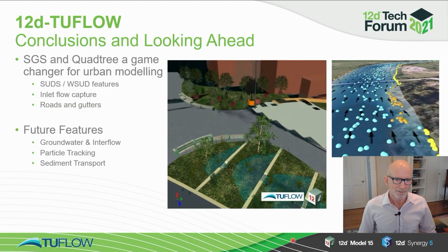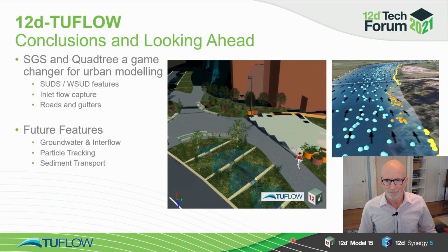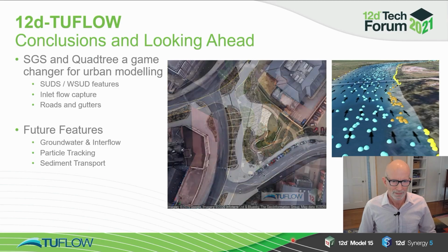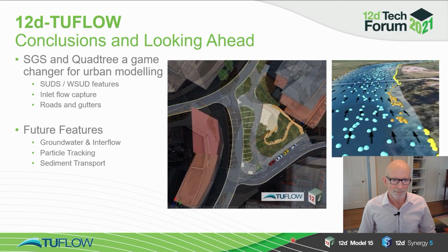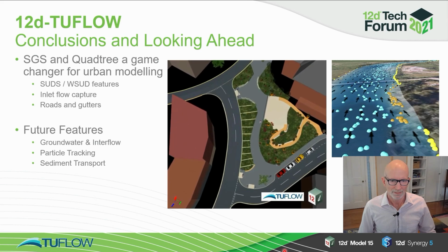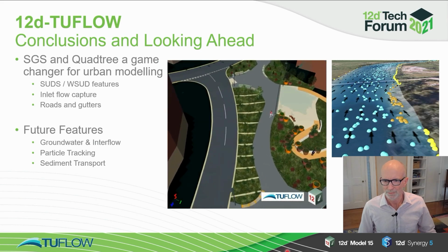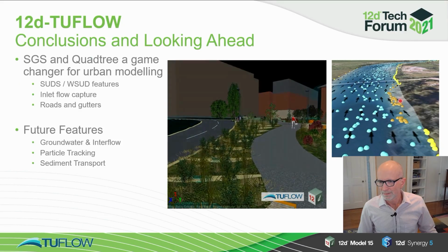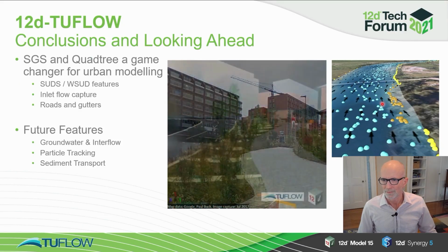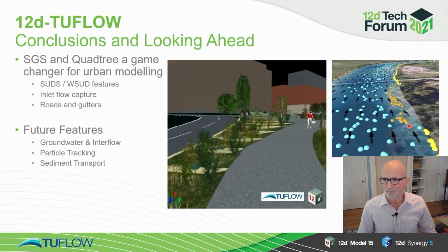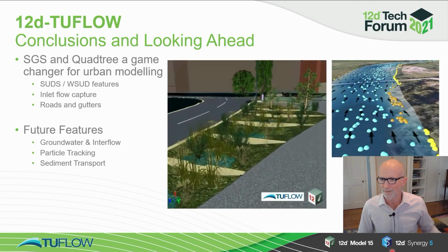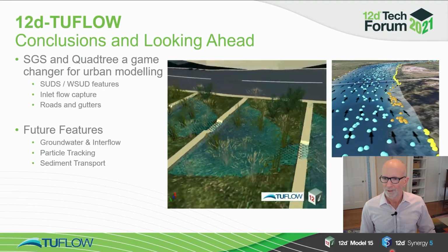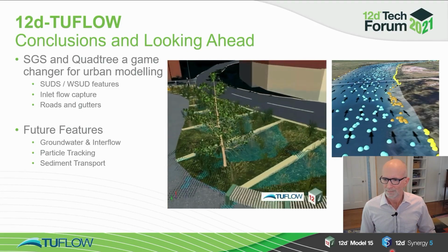Future features: we're building in groundwater and interflow at the moment. That's going to be really nice for catchment modelling, and Rob's planning to make use of those. Particle tracking and sediment transport are a couple of other big functionalities that we're building in. Particle tracking is a nice one. You can feed thousands of particles into TUFLOW, and then track where they've been and collect information on how fast they've moved, and lots of other things. That way you can get a time history of where your water's been and what's been happening.